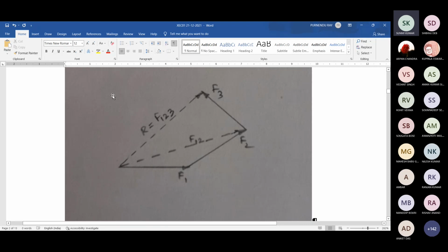Once we get these two quantities, square them, add them, and get the square root; that is the magnitude of the resultant. Divide the algebraic summation of y components by that of x components, and we get tan theta, the direction of the resultant with the positive x-axis, horizontal towards the right.